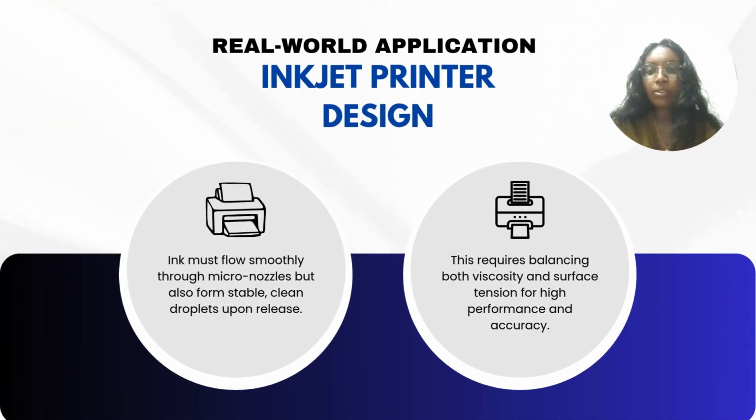Now, let's look at a real world application that involves all three properties, viscosity, density, and surface tension, which is inkjet printer design. These printers are used in everything from everyday printing to precision medical devices that dispense fluids. The goal is to push fluid through tiny nozzles while also forming clean and precise droplets. This requires a balance of viscosity and surface tension for high performance and accuracy.